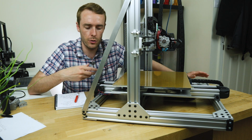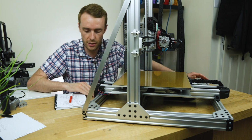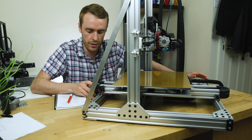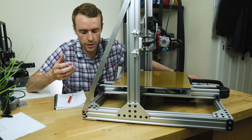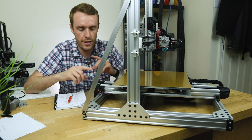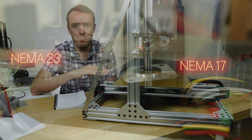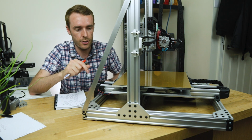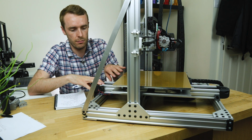So the next upgrade that would come with that, all at the same time, would be to increase the size of the stepper motor. So potentially we can just increase the body length of the NEMA 17, as body length typically translates to maximum peak torque or holding torque. But I think the more likely scenario is that it would be wise to move to a NEMA 23. So a much larger body, and therefore much higher torques. So that will be then really capable of flinging that massive bed around. So I wouldn't have to consider changing the materials or thicknesses of that bed, and it could stay as it is. So yeah, at the moment, the two options are: reduce the mass of the bed and keep the kinematic system, or change the kinematic system and keep the mass of the bed.